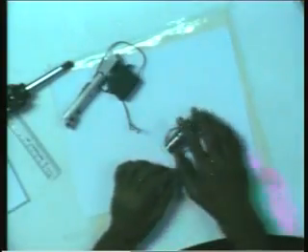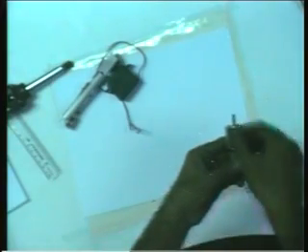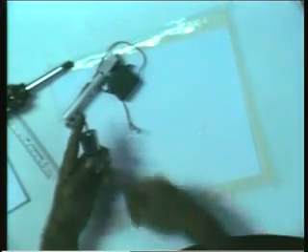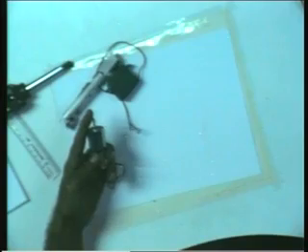These are the various things which are being used. So these are the various actuators which are being used. Mostly you find the conventional actuators being used very heavily, but the trend is towards using these high-tech actuators. The linear motor, I shouldn't call it that, I should have put it probably in the conventional. Take a conventional motor, cut it and unwrap it. So you have all the coils of the armature spread out. You keep the magnets and then the solenoid, or reverse. Instead of rotating, you unwrap it.